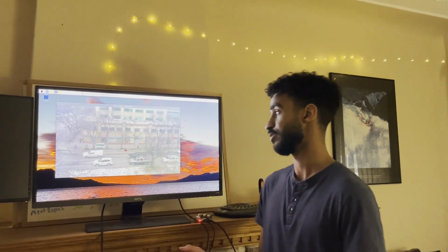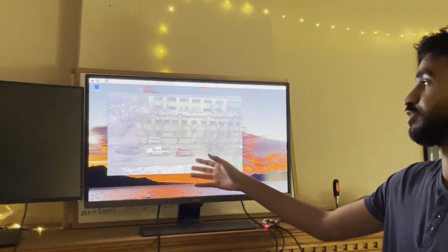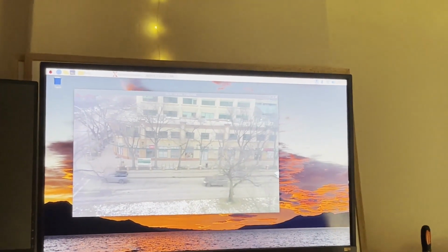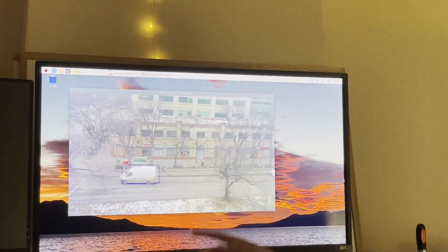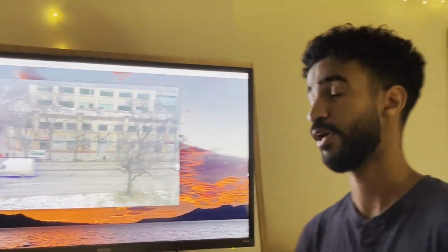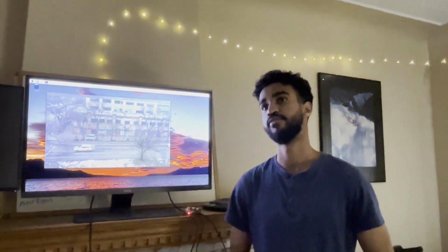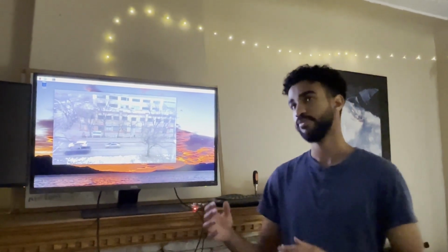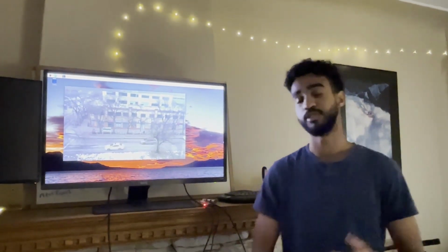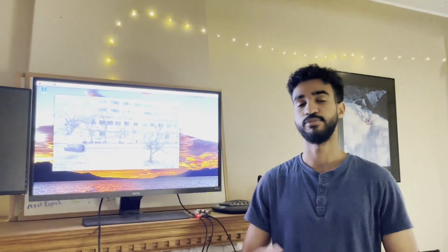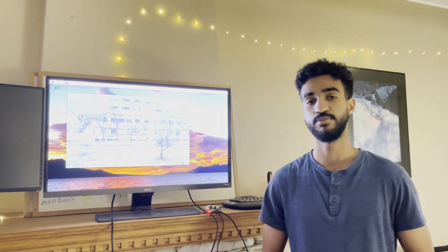The detection model is where we faced the most issues. As you can see from this video, some of these cars are being classified really well, however, others aren't really being counted. And it's mostly to do with the dark cars. We tried a lot of different architectures, and the main challenge here is trying to find a good enough model that will still run in real time on the Raspberry Pi. After attempting to fine-tune our own, none of the results were really satisfactory, and we were only able to get up to around 60 to 70% counting accuracy when we were initially aiming for 90%.